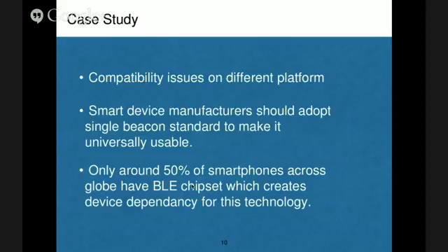The parameter or the broadcasting interval on which the iBeacon broadcasts is a bit different than how Android phones handle the beacon. So basically, iBeacon can't be directly found or scanned by the Android beacon stack. These are the parameters which are getting affected by the proprietary stuff people are introducing, so it's actually creating compatibility issues on the different platforms.